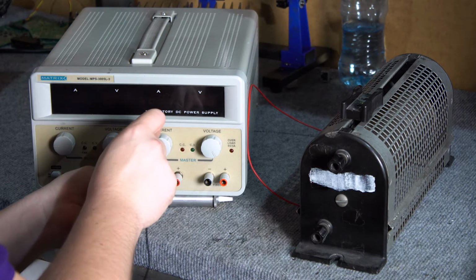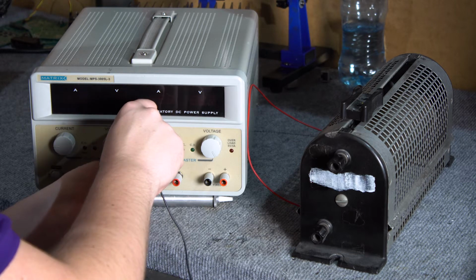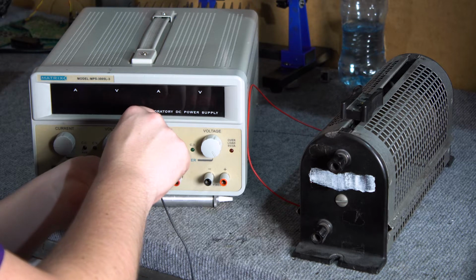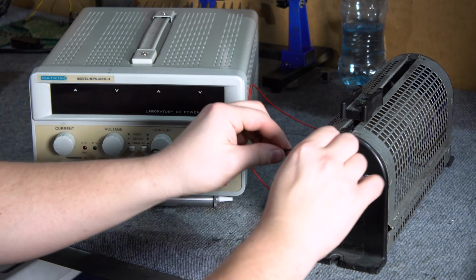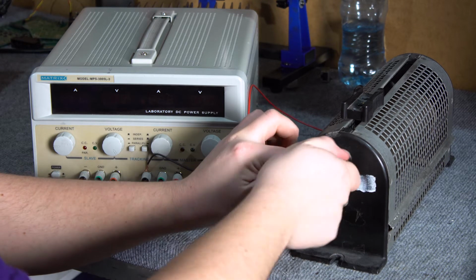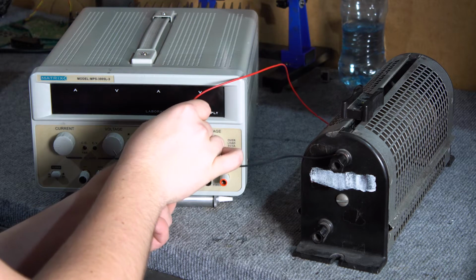Setting the voltage to a value of, for example, 5 volts, we expect that it will be constant. The system then acts as a voltage stabilizer, constant voltage, CV. When we set the current to, for example, 100 milliamperes, until we exceed this value, the voltage will not decrease.